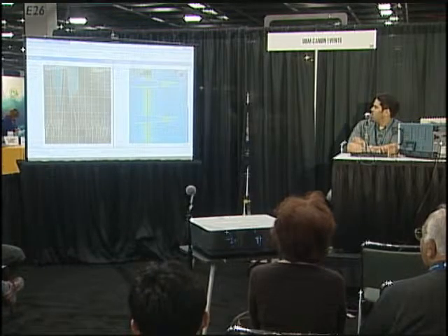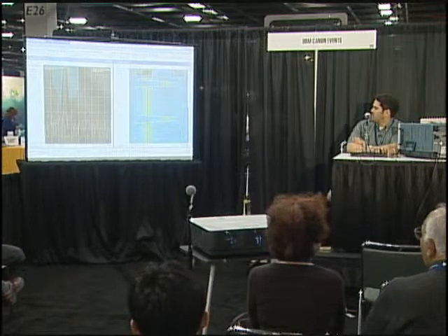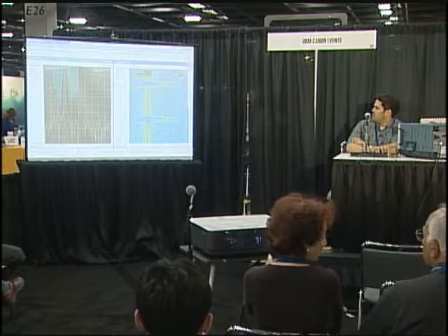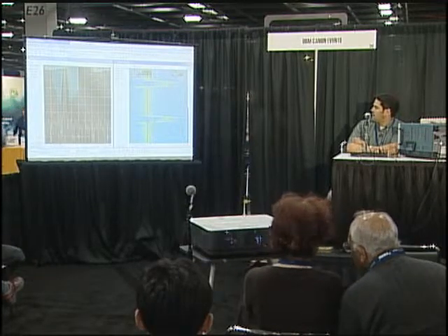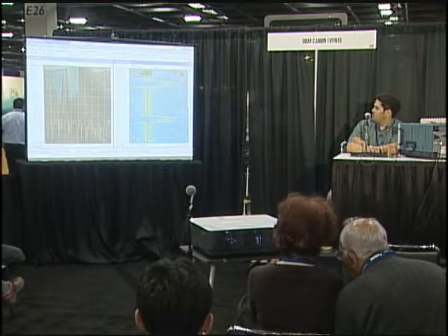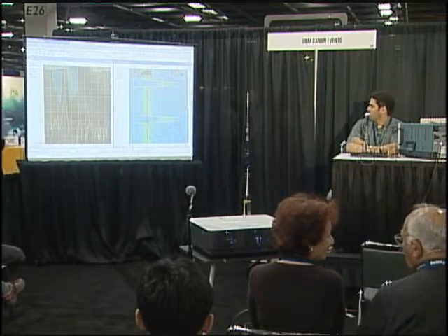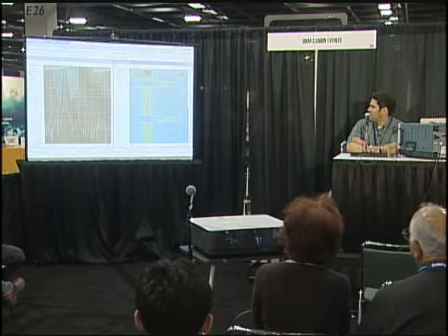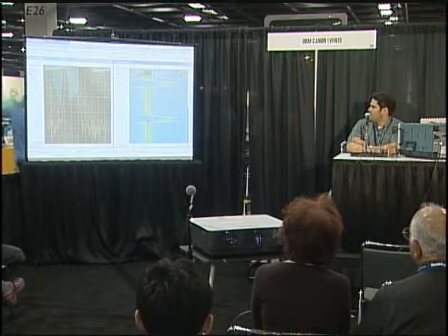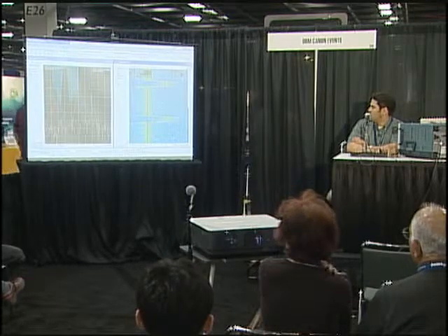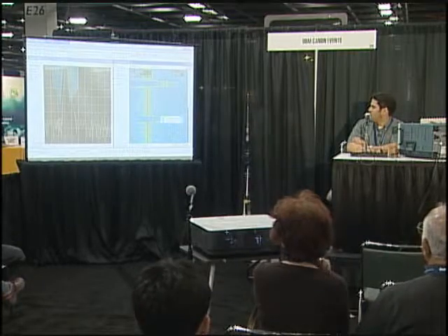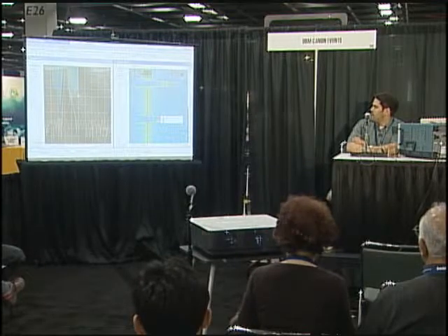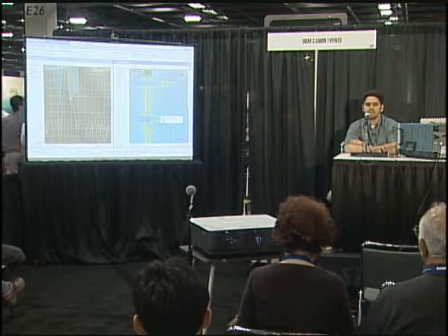And I want to show how these acquisitions happen. So you can see here when I move the cursor up and down that we are changing the position of the spectrum display in time. And I'm going to go to the trigger position here. And when I get close to the T, you see how the signal hit the mask right there. Right there. So this acquisition of 1 millisecond from here to here happened because the signal hit the mask over here.